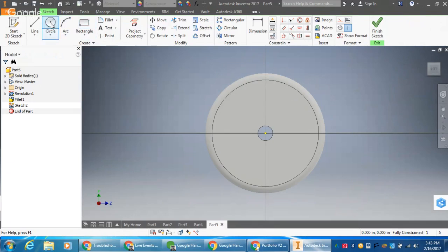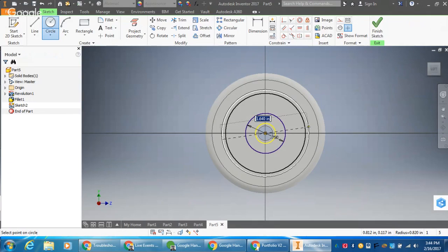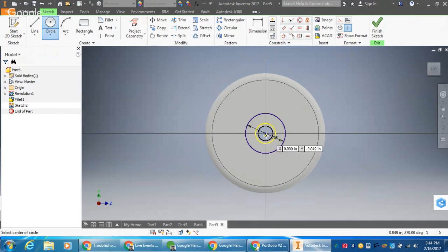So what I'm going to do is start off with this circle here. And this smaller circle, if you look here, is pointing at a radius of 0.375. So 0.375 radius, but since I'm making a circle defined by its diameter, I'm going to multiply that by 2. And then you have the outermost of these little shapes. I'm going to hit escape. Sometimes it'll stop and give you something you don't want, and that one is going to be 0.625. And again, it gave us a radius, so we have to multiply that by 2 to give us a diameter.